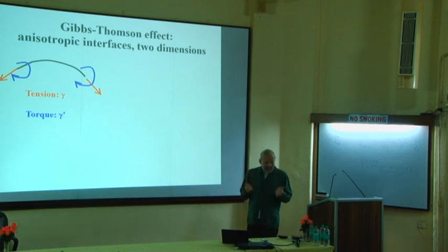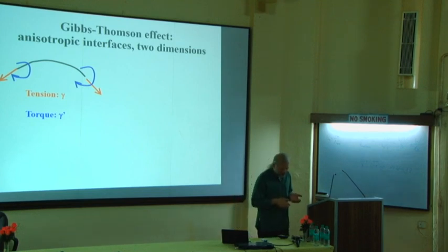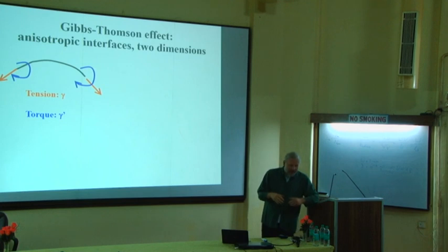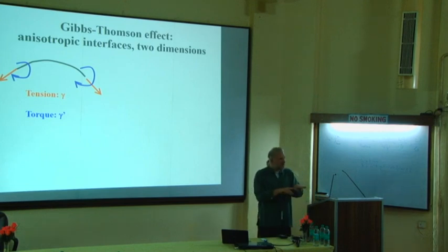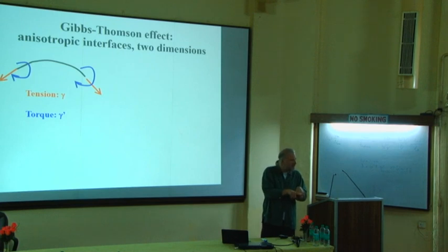Now there is a very intuitive picture to understand the boundary condition that will appear. You can interpret the surface energy mechanically as a surface tension. Surface energy is an energy per unit surface. You can also see that as a force per unit length. So if you cut the surface, and if you try to hold it, the surface tension will exert a force which is proportional to the length along which you cut.